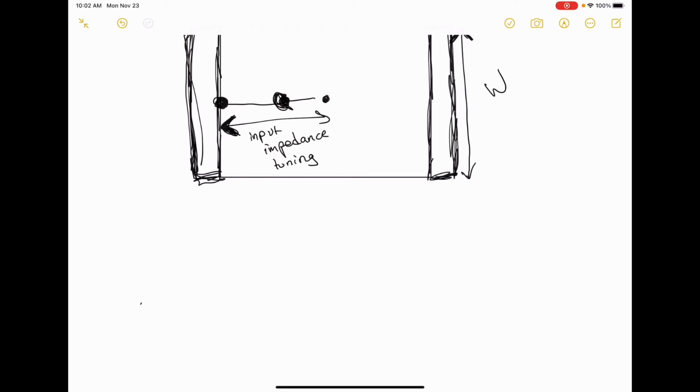The way that this antenna radiates is a little weird because we have a horizontal current, right? I said that we have this current that's on the surface of the patch antenna, and it's closely spaced to a ground plane because I said that that spacing, h, is much less than a wavelength.